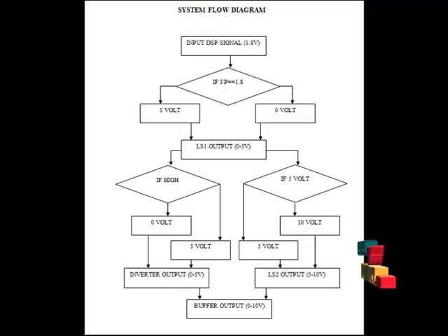The pulse width, the period, and the required amount of generated acoustic pressure, which relates to the maximum voltage of the output pulse signal, are decided at the system level depending on the specific medical imaging application as well as the device characteristics of the following transducer.